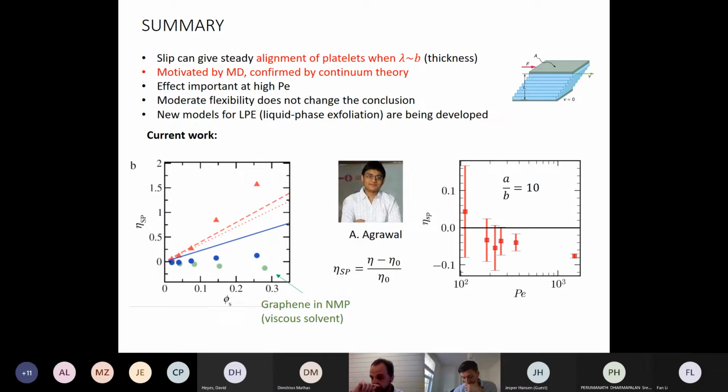I believe the result is actually physical because the viscosity is just a measure of the friction between fluid layers. Now, if you can imagine that you can replace one of these fluid layers with a solid particle, and if this solid particle has a reduced friction with the other liquid layers, it is perfectly conceivable that the entire system has a reduced friction to sliding, a reduced resistance to sliding.